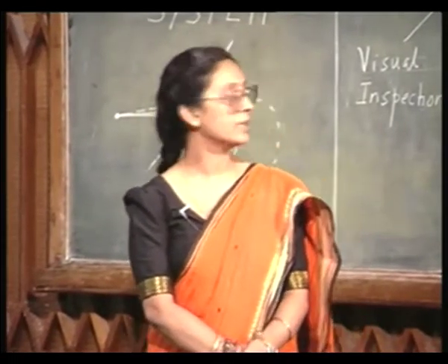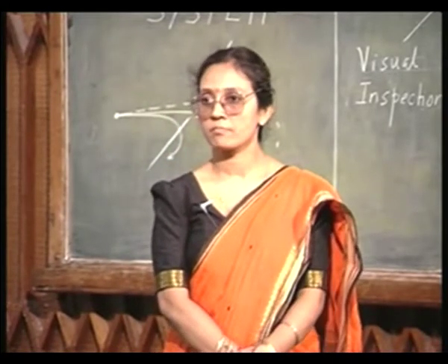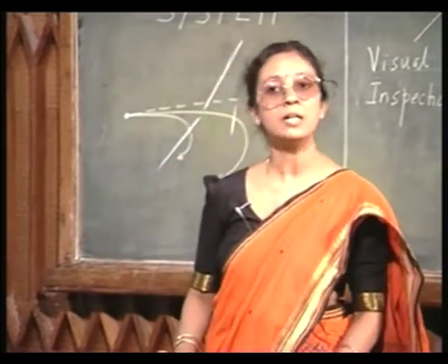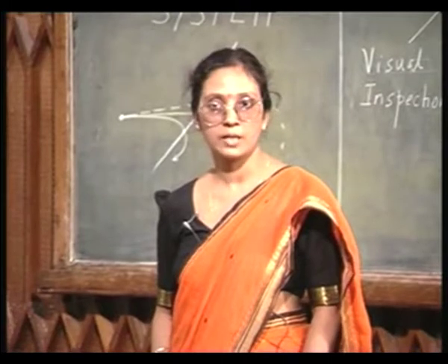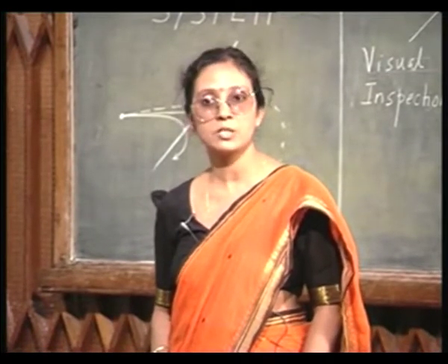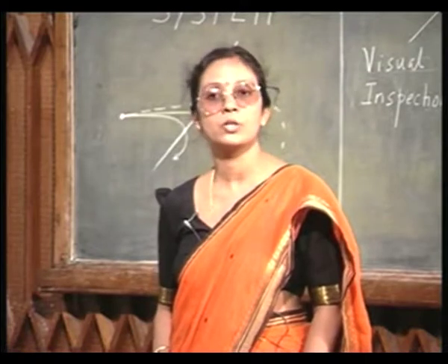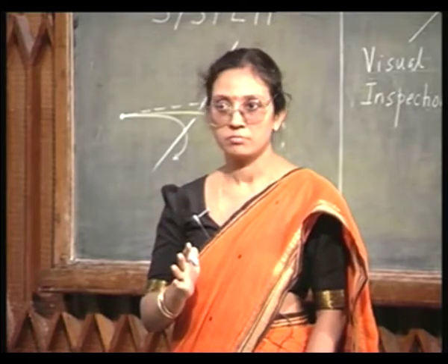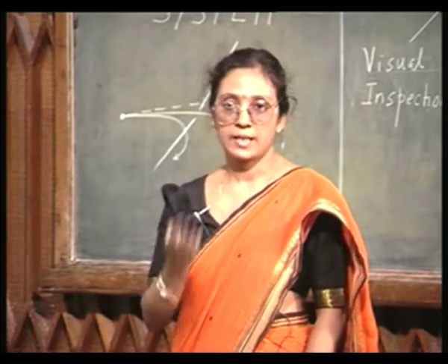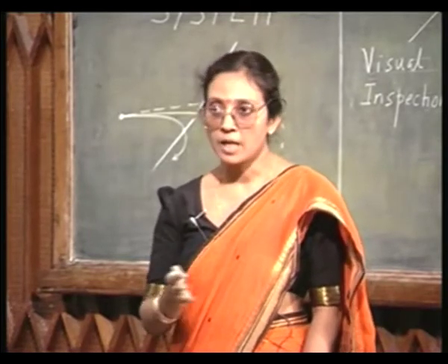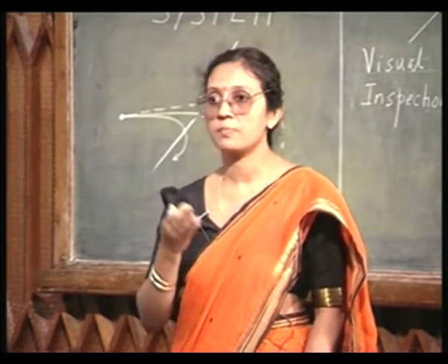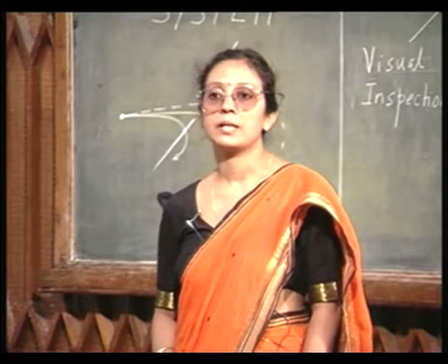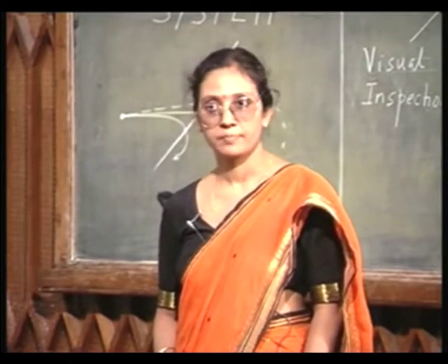I have to get back the electronic activity, that is I have to get the active carrier concentration. You see, I may have put so many dopants inside the semiconductor by ion implantation, but they are not electronically active. That is why the resistivity is very high, rho is very high. I must get the active carrier concentration. Secondly, the mobility of that damaged region will be extremely low. I must get back the expected high mobility, and then I must get back the expected carrier lifetime.